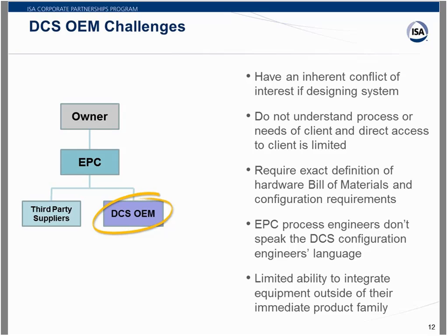And probably the biggest issue for the DCS vendor is that typically a DCS vendor is not so good at integrating equipment that's outside of his family. He's good at what he sells, he knows that, but if he's brand X and there's brand Y and brand Z that it needs to talk to, like on the skid package, you've got communications interfaces you've got to deal with, that's not going to be something he does well. And he's going to definitely struggle with that side of it.